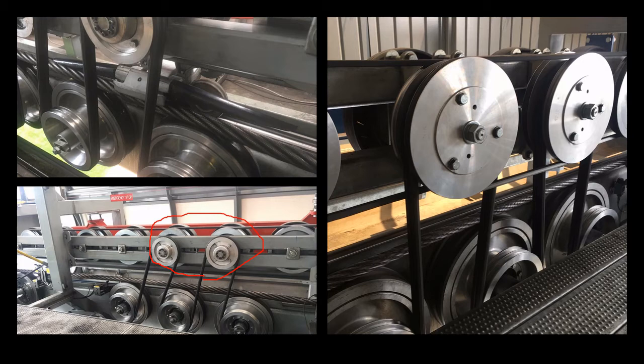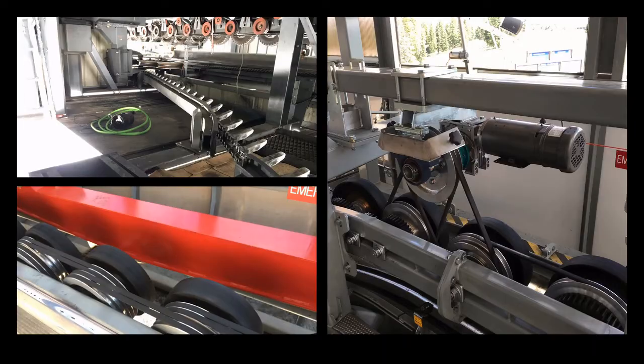The acceleration and deceleration regions are created by adjusting pulley ratios to move the tires faster or slower relative to one another. The advantage of this system is that since it is directly tied into the haul rope, the speed of the tires will always be proportional to the speed of the lift. The image on the bottom left shows the rubber belt connection between tires in a tire bank.